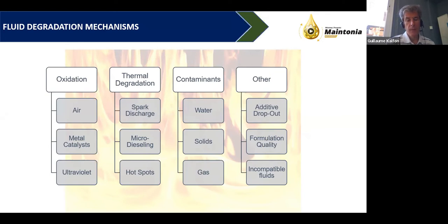The general quality of the oil formulations that you buy, they're not all the same. Don't go thinking that a hydraulic fluid is a hydraulic fluid is a hydraulic fluid, and whatever you buy will be the same performance and the same quality. That's not the case. And same for industrial oils, for turbine oils and compressor oils. They don't all have the same quality. And finally, incompatible fluids. Frankly, all of us here like to think we are infallible, but no human being is infallible. Sometimes we may have human error, so a top-up of a wrong fluid inside your industrial oil may happen, and that is an unfortunate event which will cause degradation of the oil.